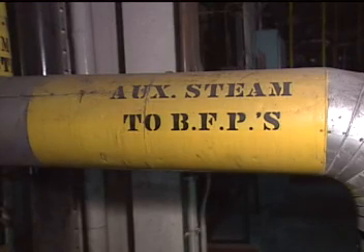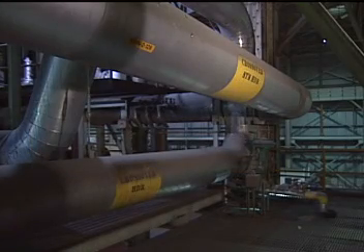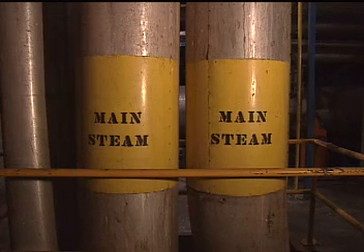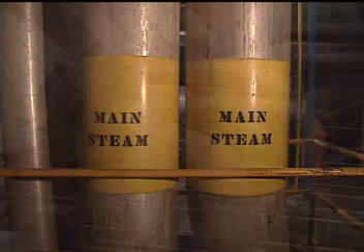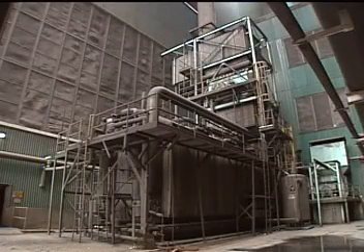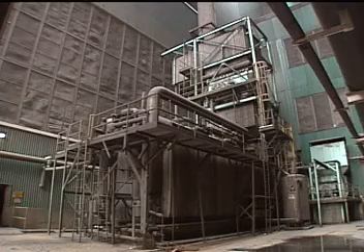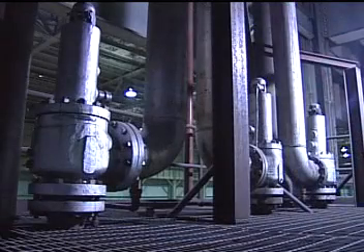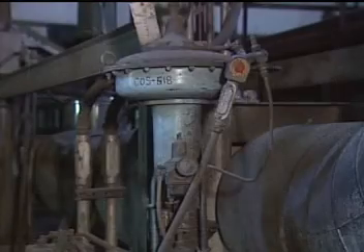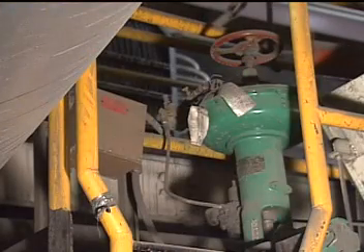As we've seen, there can be many uses for auxiliary steam in a plant. The exact source of this steam depends on the plant's design. But during normal operation, auxiliary steam is usually supplied by either the main steam system or the extraction steam system. In some cases, auxiliary boilers are used to supply auxiliary steam when a plant is shut down. Regardless of the specific design, though, most auxiliary steam systems have certain protective devices and control components in common, such as safety valves, pressure regulators, and temperature regulators.